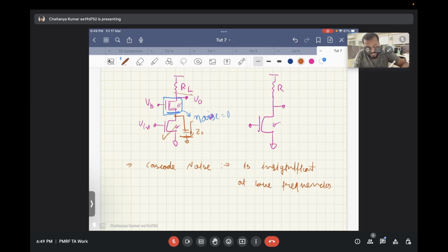As far as noise is concerned, you need to size this cascode transistor in such a way that, till the frequency of interest, the noise from this transistor is insignificant. You can increase the GM of this transistor by having a higher size of this transistor. Apart from that, if the noise from this transistor is still significant, the other thing that you can do is...